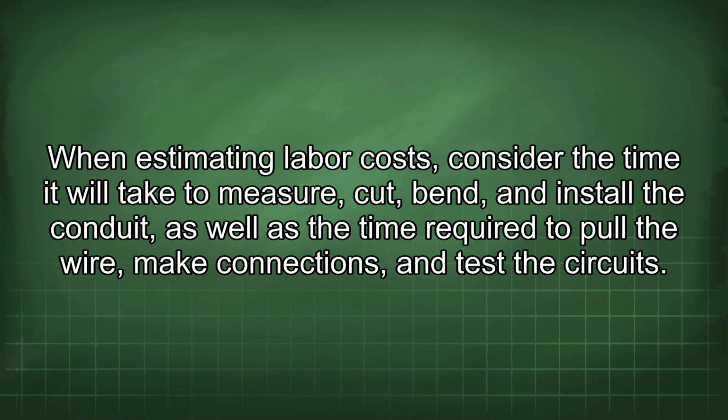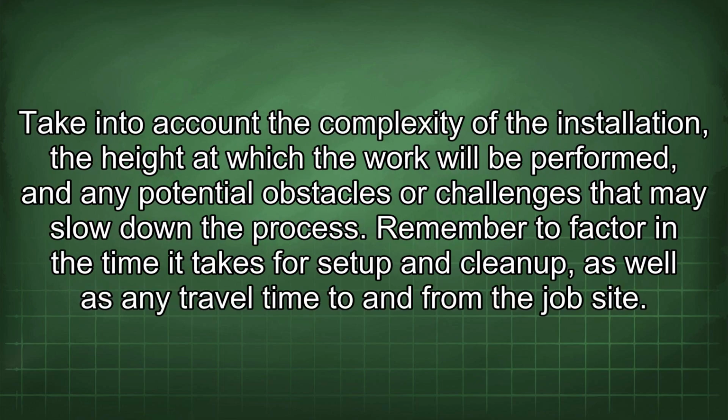When estimating labor costs, consider the time it will take to measure, cut, bend, and install the conduit, as well as the time required to pull the wire, make connections, and test the circuits. Take into account the complexity of the installation, the height at which the work will be performed, and any potential obstacles or challenges that may slow down the process. Remember to factor in the time it takes for setup and cleanup, as well as any travel time to and from the job site.